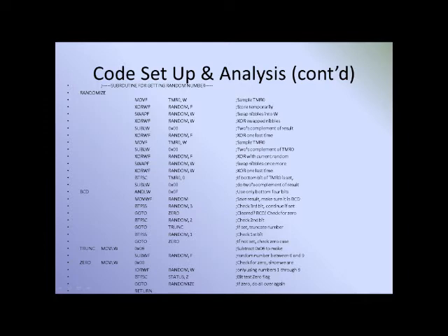Then the program bit tested the limited value to see if it was between A and F. If it was, the value was truncated by subtracting by 6. The next condition that needed to be checked was whether the new value was 0. Because this experiment only used a 3x3 keypad matrix, which only included numbers 1 through 9, if a 0 was generated, there would be no way for the user to input a 0 from the keypad.